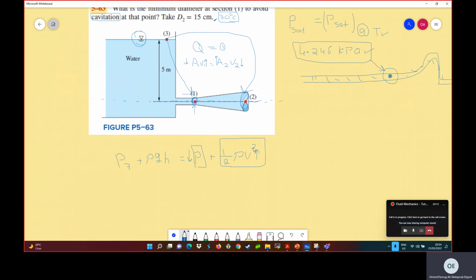So whenever you increase V1, because V1 is higher than V2, then P1 is less than P2, okay? And this applies also for any point here. Not necessarily point one exactly, any point that has the same cross-section here. Because if you apply the Bernoulli equation for everything here, it's at the same elevation and we have the same cross-section area, so you have the same Bernoulli equation.